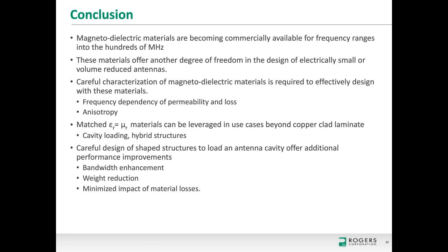But it just imports directly in, and then it performs, I believe, a linear interpolation between those two frequency points. So if I'm giving you a value at 101 megahertz and 103 megahertz, and we're operating at 102 megahertz, it'll take a linear average between those two values.